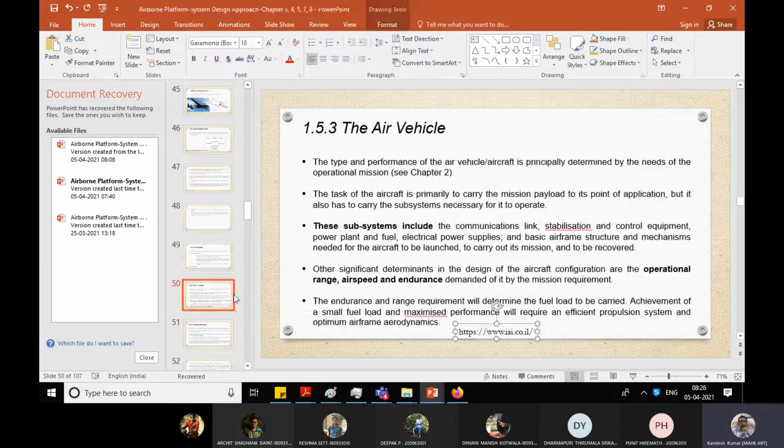When we are talking about this type of platform, the main task is that the aircraft should be stable, that is no doubt. Then flight performance. If not, then you should go with a low payload capacity, or design other vehicles, correct? So the first idea is that you should have the payload requirement, meaning the weight of payload it can hold, and second is the endurance. These two are very important. If you can support them, then only can you talk about the range. So flight endurance and payload are the very important parts when designing the UAV.